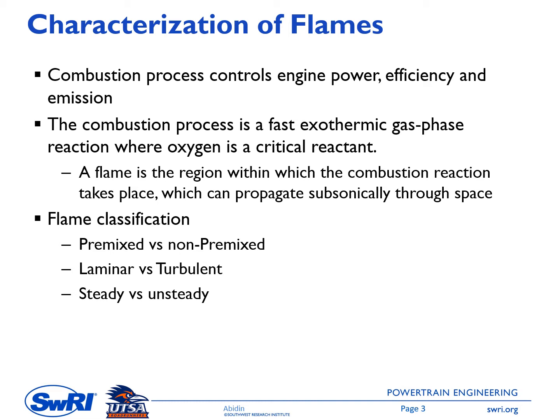And then we might have a non-premixed combustion. This is the case for diesel combustion. We have air inside the engine cylinder, and then we inject the diesel, and then the combustion occurs maybe several crank angles after the injection process.